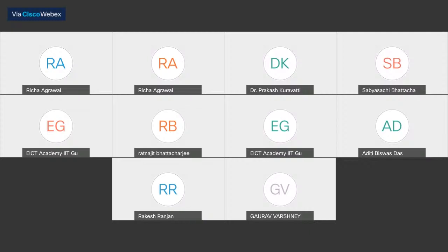If my antenna does not have good cross polar isolation, it will pick up both. Along with X, it will pick up some components of Y, which is undesired. So that's why we need to design systems where the cross polarization is very, very low. Cross polar components are suppressed, and cross polar suppression techniques are used in many antenna designs.